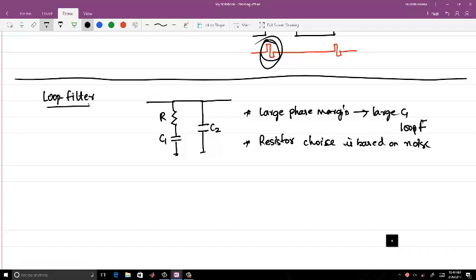your MOS resistor here or something. Means you can try to do this, but right now I would say do not do these kinds of things. Let's say if I go and use all active devices, and this also becomes a capacitor, and interestingly you can say I'm using very less area and I am doing this, with gate capacitances on both the sides. Can you just tell me what the issues will be? We will deal with the issues later. Gate leakage.